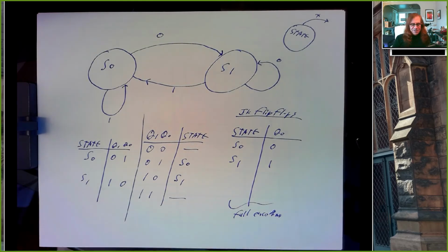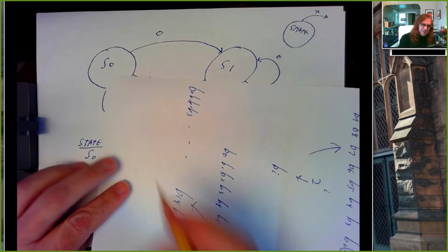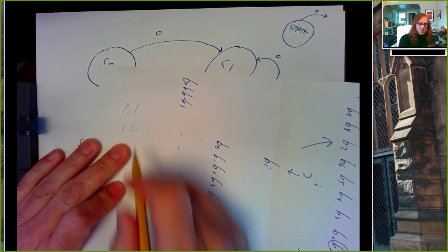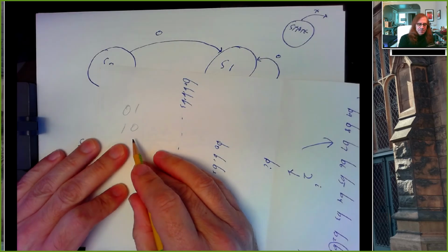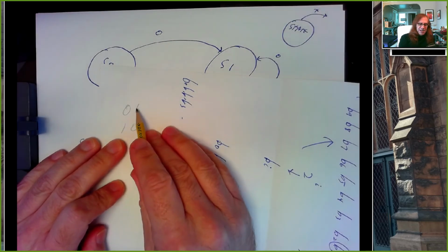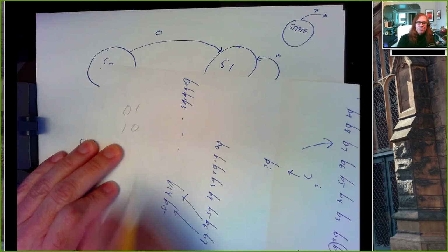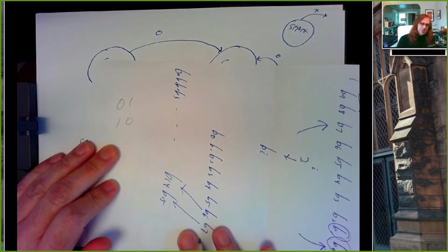And if we are building circuitry that's going to move from one state to another, here's the situation. If we change from state 0, 1 to 1, 0, this bit has to change from a 1 to a 0, this has to change from a 0 to a 1. We don't know the order in which those things are going to happen.